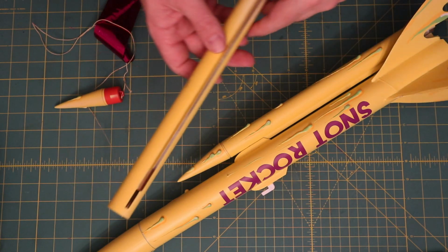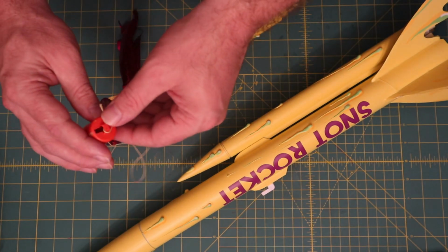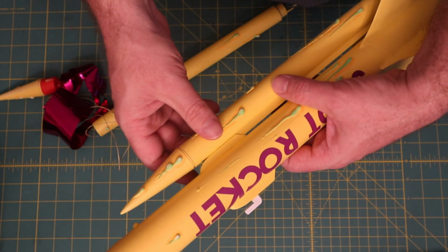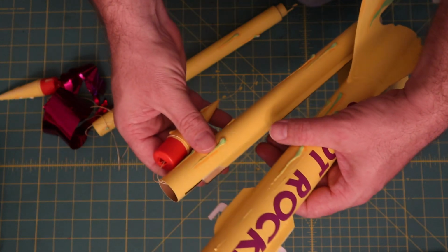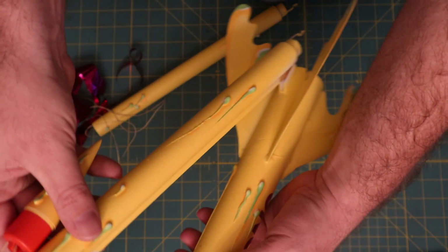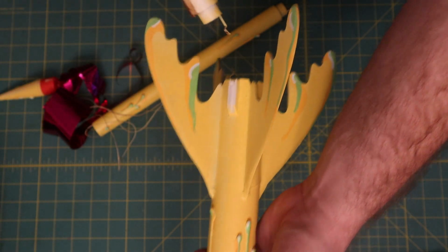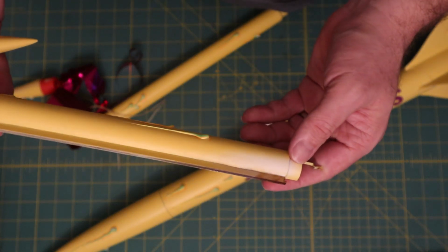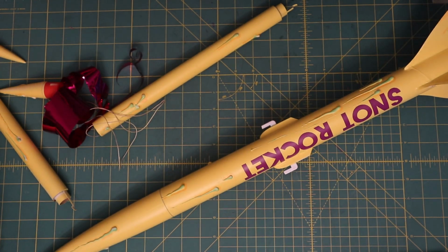But before we do that, we wanted to provide a little more detail on how these boosters operate. So you'll see there's a hole in the nose cone that mates through the body tube onto that hook. So when the ejection charge from the booster fires, the nose cone pops off, allowing it to lever that way and separate from the body. So you do use the standard booster motors with a 0 delay on that, and that's sufficient so far to get the separation of the nose cone.